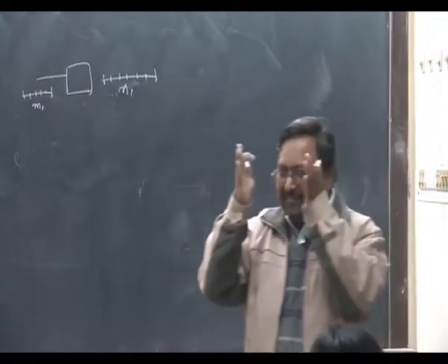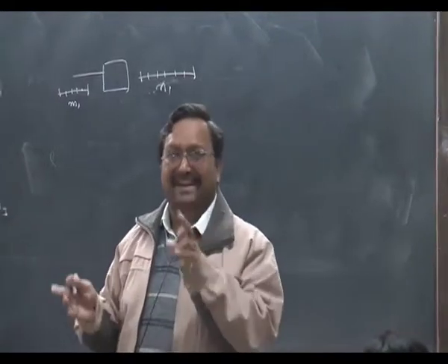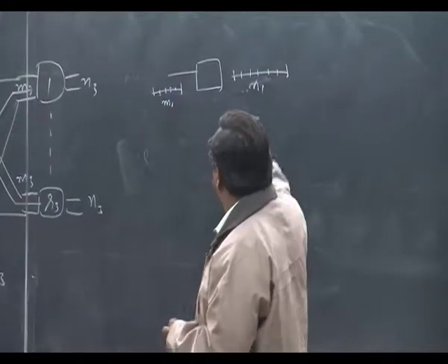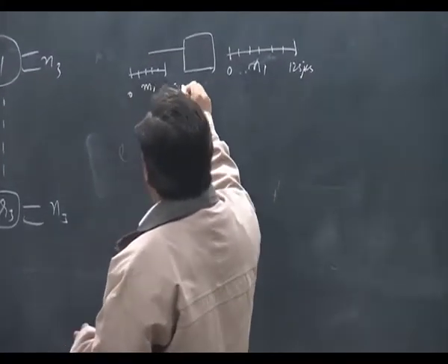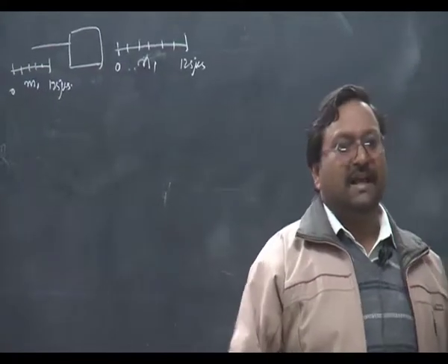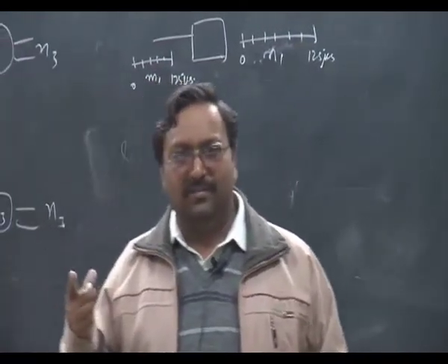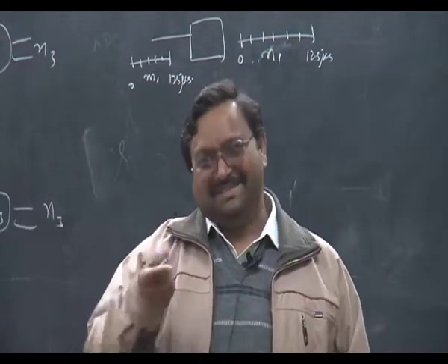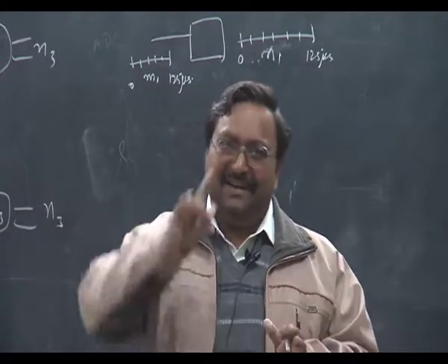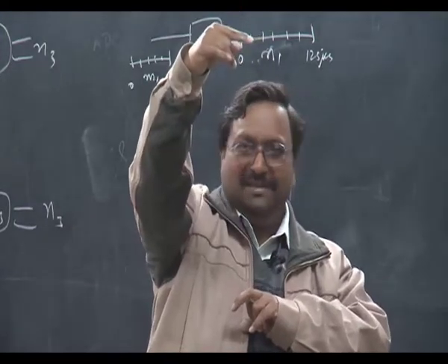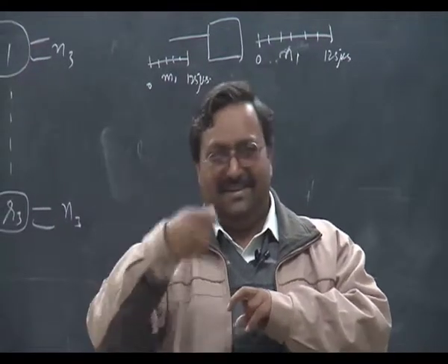The whole octet, the whole frame has to be written first in the memory, then only it can be read out at a different rate, because remember the frame duration is still 125 microseconds. That does not change. In reality, I will do this implementation of the M by N time switch later on. We actually use 2 RAMs. When the first frame is written in the first RAM, only writing will be done. Reading will be done from the other RAM, with a different clocking rate, so that you can read faster.